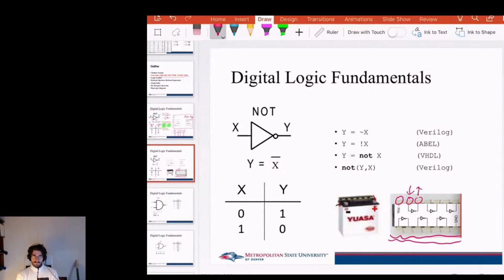Of course, for the IC to be able to work, you have to have power, because this is a digital circuit anyway. You can easily use a small battery to generate 5 volts and connect the IC to make sure it is powered, and then the gate will generate a logic 0 or 1.